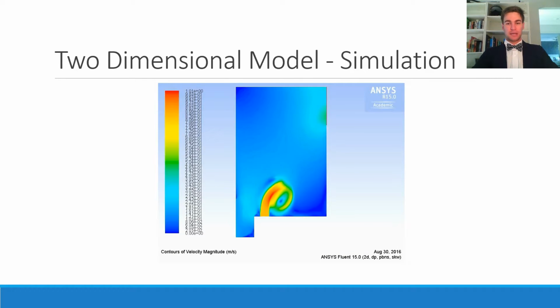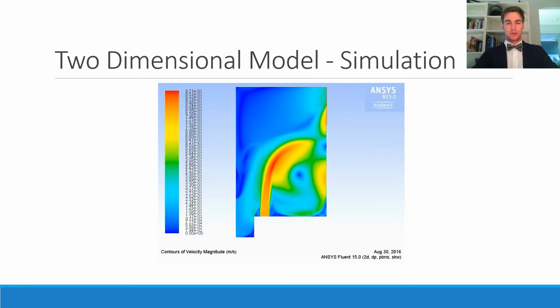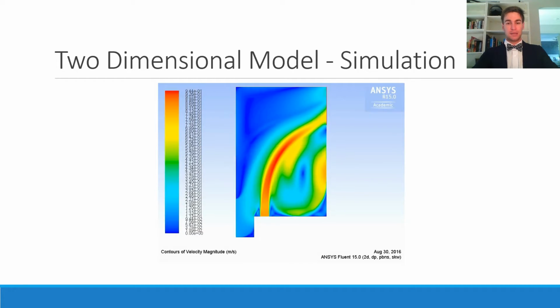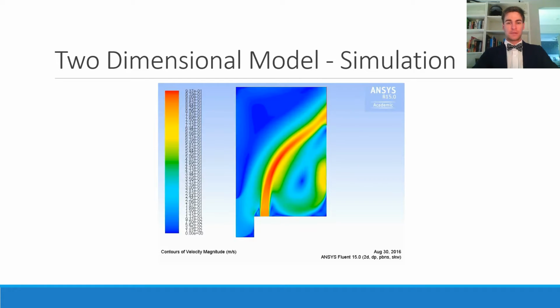The simulation is of iteration E for the k-omega standard model. This is a top view of the zone with the inlet in the bottom left-hand corner. The outlet is in the top right corner, and the A-recycle pump is adjacent to the inlet and along the bottom edge. The mixer has been neglected from the simulation to evaluate the hydrodynamic performance without its influence. The flow from the A-recycle pump is prominent through the zone, and it can be seen that its curvature towards the outlet is influenced by the flow from the inlet.